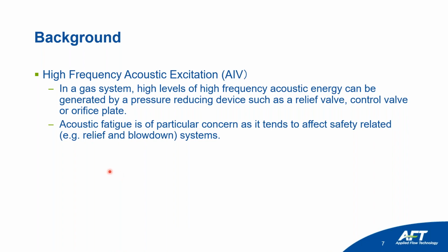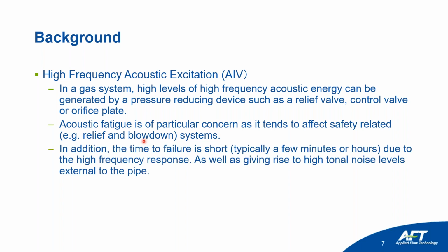Acoustic fatigue is of particular concern as it tends to affect safety-related systems, such as when a relief valve opens or when you have a blowdown operation. One particular thing about acoustic excitation is that the time of failure can be short, typically in a few minutes or hours due to high frequency response, as well as giving rise to high tonal noise levels external to the pipe that can create a hazardous condition for the